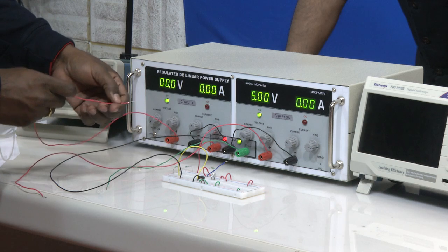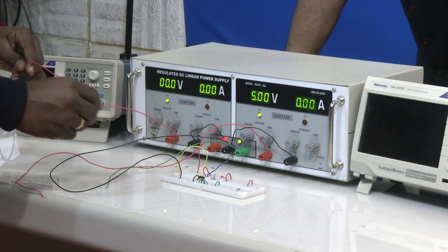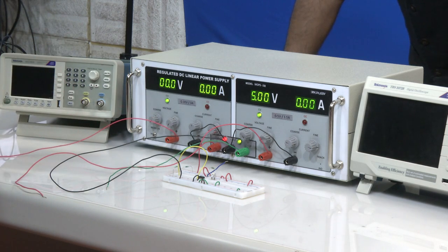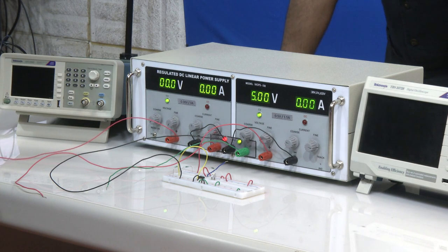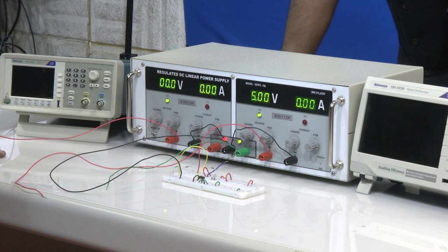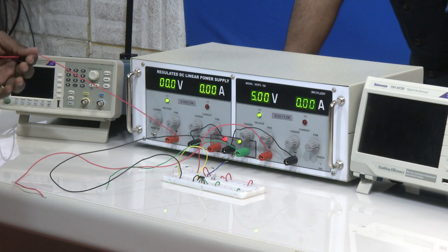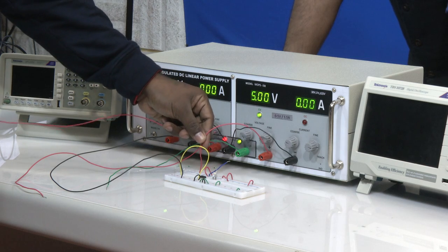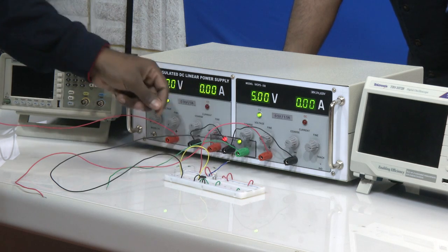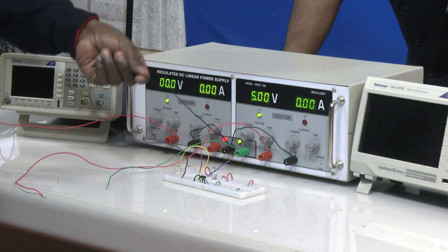In this case, since our circuit requires plus 5 volts and 0 volts, that is why we are applying plus 5 and 0, not plus 15 and minus 15, for this particular comparator circuit. Now, we have connected plus 5 volts to plus VCC, as you can see on the DC power supply, and ground to the minus VCC, alright.